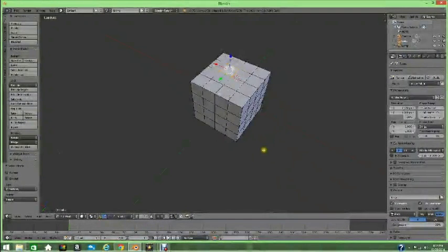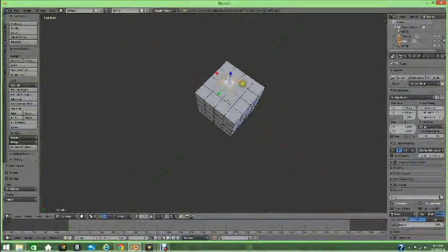The last selection type we will cover is the Control. If I select the center vertex and then hold Control and hit my plus button on my number pad, it will select the vertices going out from center. This can be a useful tool. It also works if I switch over to face mode by holding Control Tab, clicking face. I'll click on one face, hold Control, and hit plus, and it will select all the surrounding squares.